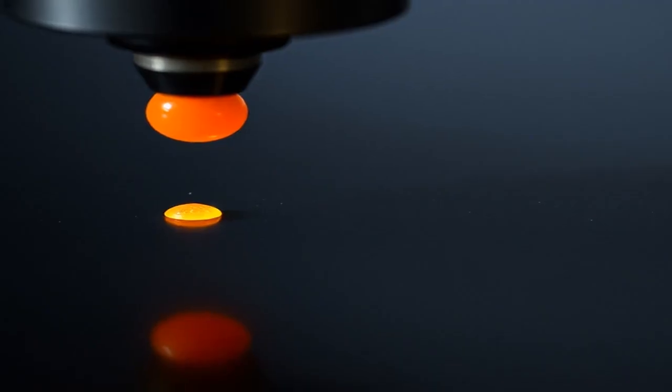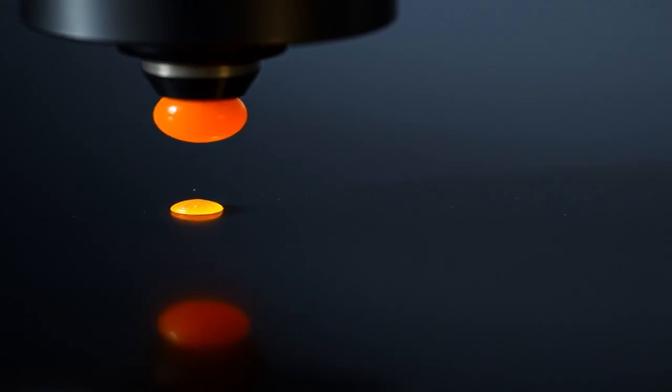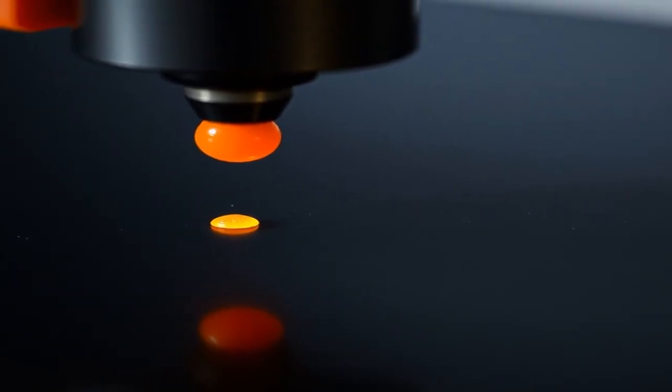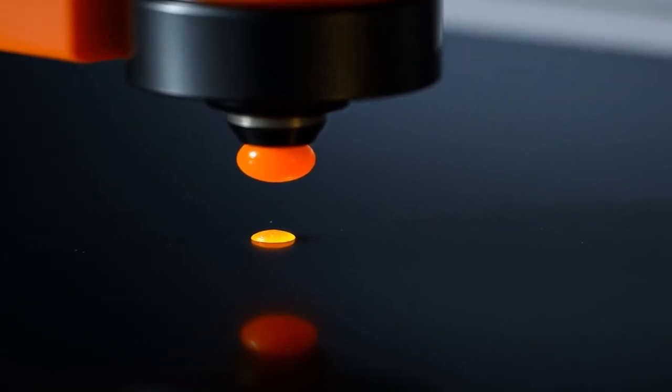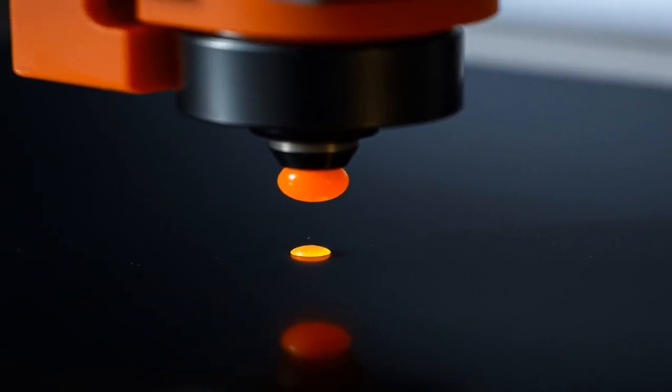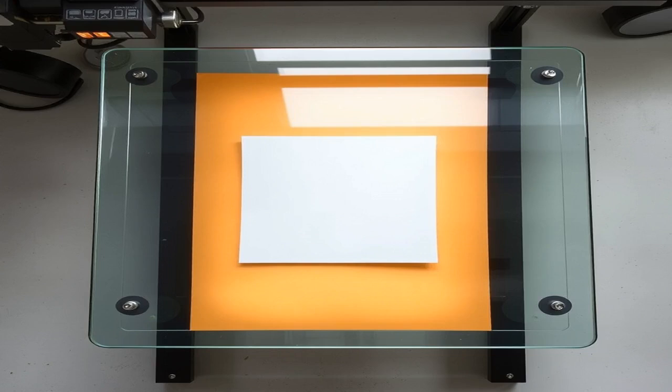The position of your print depends on these settings. The extrusion width determines the thickness of each line, while layer height controls the vertical resolution. To ensure the object stays put, the print bed must adhere to the first layer. Proper adhesion prevents the edges from lifting or warping as the plastic cools.